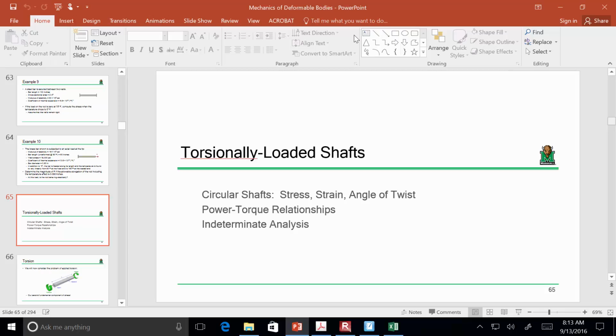So what you should be able to do is determine the area of all those steel cables, and then load divided by area will give you stress. Make sense? Okay, so let's see. Weight of the load. Now I'm going to read it so that I make sure I'm telling you the right thing. Diameter of middle cable.